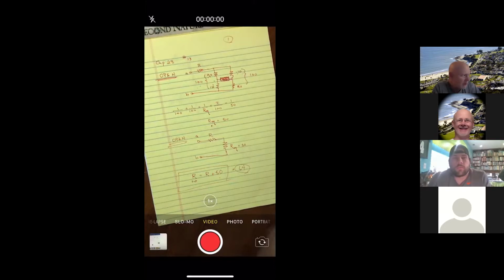that if I go under, say, an overpass, so if I go under the 101 freeway there, even though it gets dark, nothing happens for about 30 seconds. So the computer knows it went dark, but it's programmed so that unless it goes dark for more than 30 seconds, don't actually change it on your dash or your running lights.